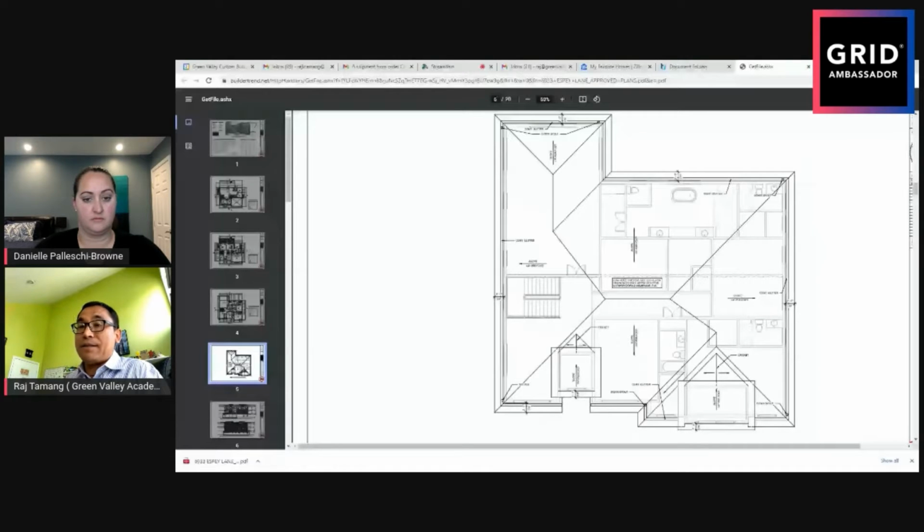For example, this house I mentioned before, this is a flat roof, but it looks like it has a slope. The reason is this is still a flat roof, but there is no such thing as a truly flat roof, because you have to remember, if it is raining, that means rain is staying in the place, right? It's called a water pond. So you can't have that. So you have to have a minimum slope, which is usually 1 in 48, quarter inch per foot. For the slope. Got it.